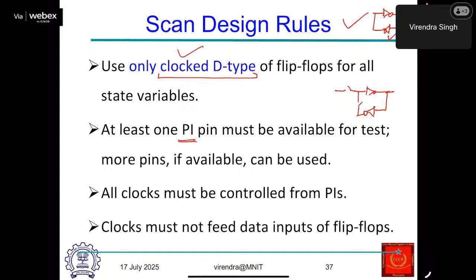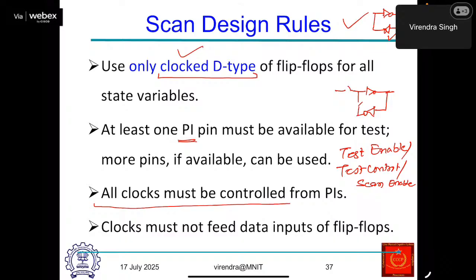At least one primary input must be available in your chip to provide the test enable pin. Test enable or test control, or scan enable. Different literature uses a different name for that. Another thing is all clocks of all the flip flops must be controlled.